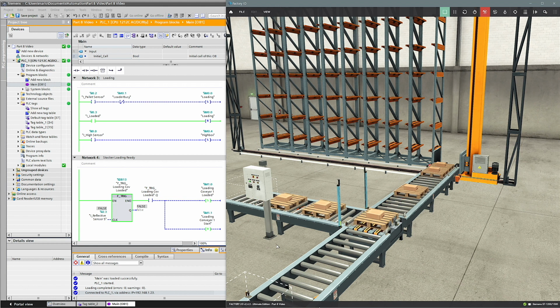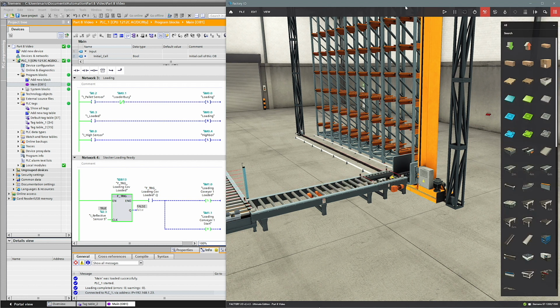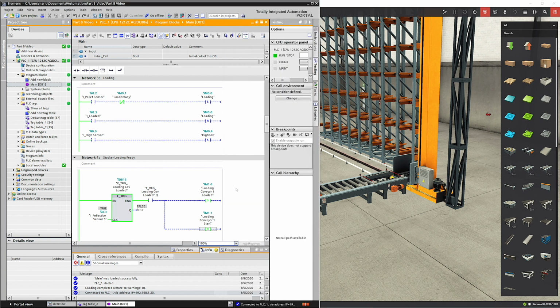The first pallet stops at reflective sensor 5, but other boxes keep coming along and pushing the first pallet onto the stacker, instead of stopping and waiting at left exit. Therefore, if a pallet has reached reflector sensor 5, we need to set a latch to indicate the stacker is busy, and any further pallets coming down the left conveyor should stop as soon as they reach the left exit sensor. Okay, let's stop the PLC and make some changes to the ladder logic code.